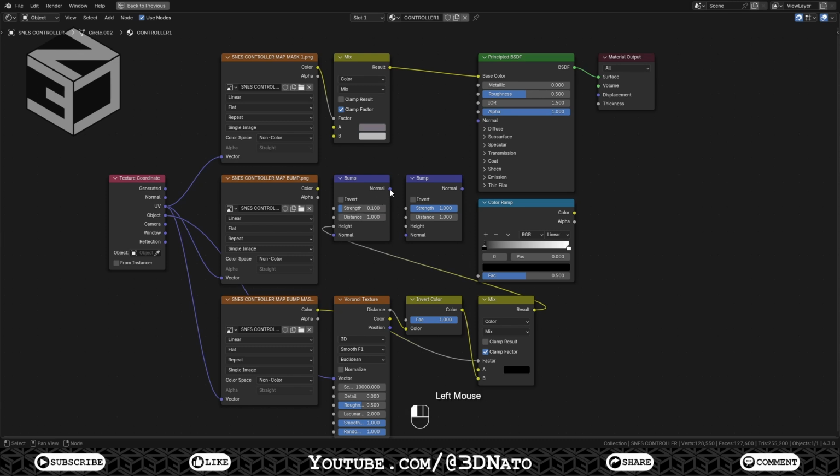Connect the first bump normal to the second bump normal. Connect the bump map image texture color to the second bump height and set strength to 0.4. As we have created a bump map with shades of gray, all lighter grays will appear to be going up, like the Nintendo logo on the plug, and all darker grays will appear to be going down, like the L and R letters from the left and right buttons. Connect the second bump normal to the principal shader's normal.